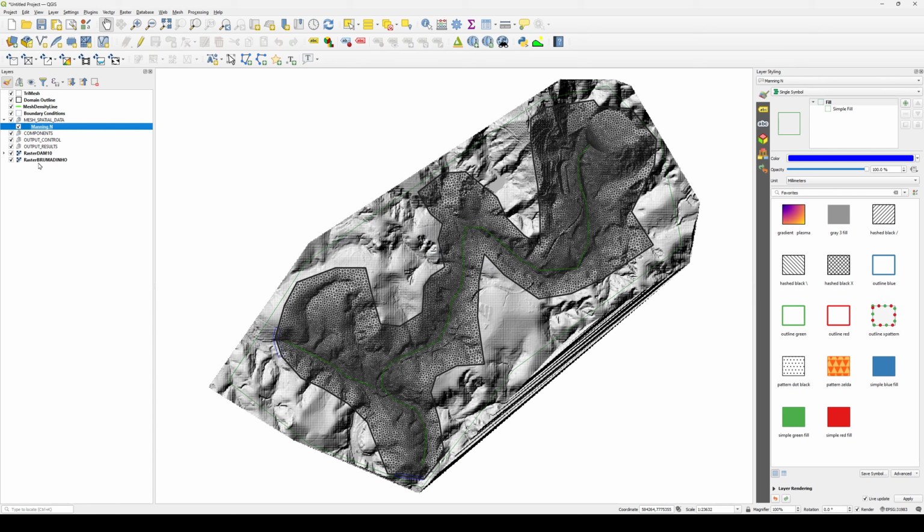And now we have a mesh. And you can see that the cells get smaller on the line, and then they get larger as they go away from the mesh density line. And this should give us a sufficient amount of accuracy for our tutorial and keep the number of cells relatively low so that the calculations can be performed quicker.